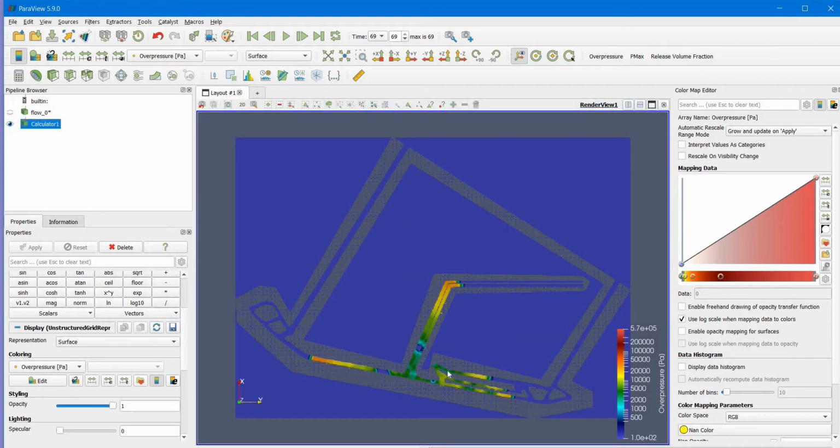So that's more than enough to cause dust to be kicked up, and you're going to get a dust cloud everywhere. And if there are ignition sources anywhere, and the gas itself is probably hot enough, it will ignite that dust cloud. So we have to go to step 3.